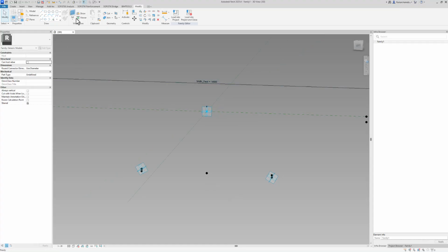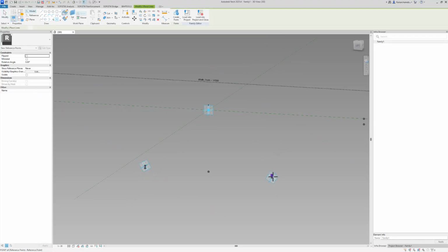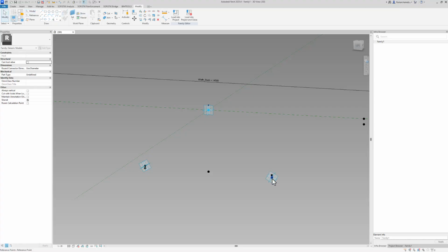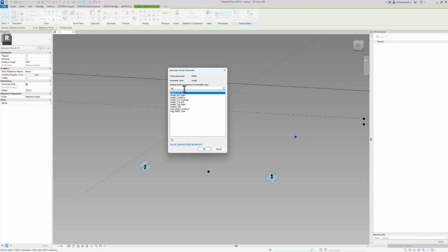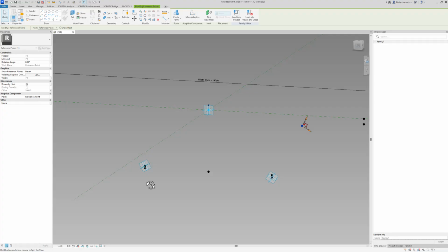What I want you to do is select the original horizontal plane of this point to create a new point in it. And what we can do is we can either just offset it by drag and dropping it on the right plane, or we can assign an offset parameter to it. And as we have the height of our web as a positive value, which goes up, already defined, we use the negative one for this point, you remember, we can use it to always have a long enough offset for this point.